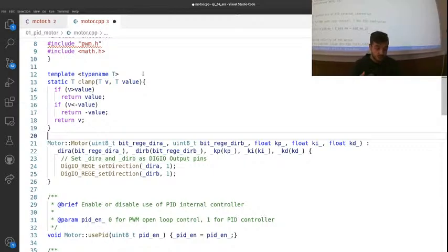As you saw, the PWM library's duty cycle function takes an 8-bit, single byte integer, while the output of the control PID is a 2-byte integer. So if we don't bound this variable in a 1-byte space, we may overflow and obtain wrong values.